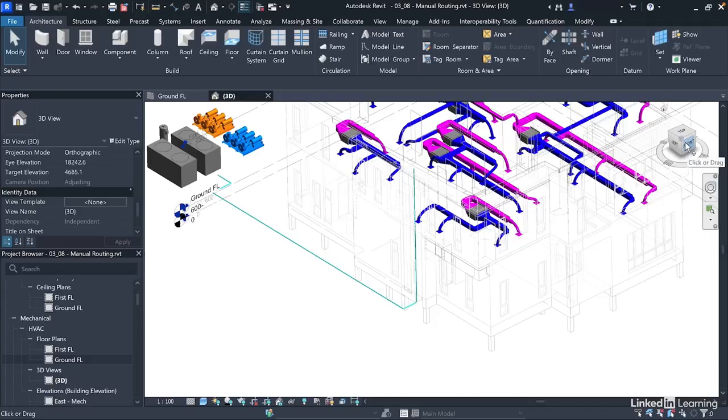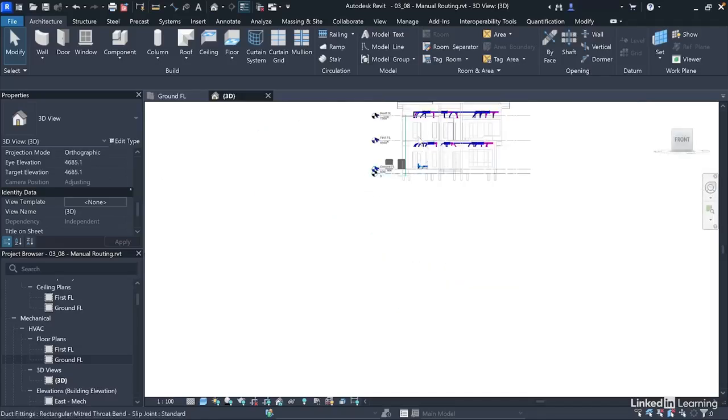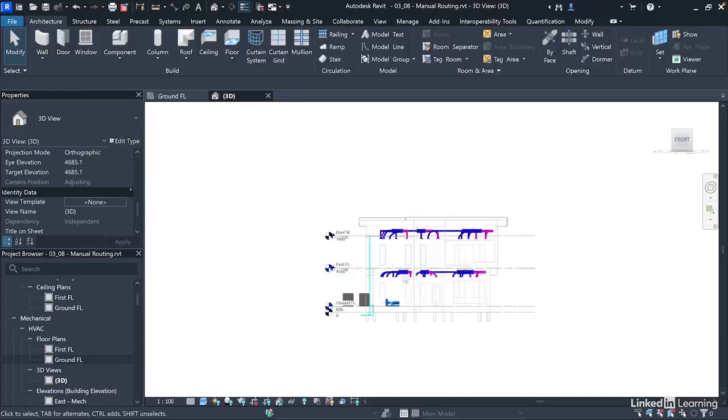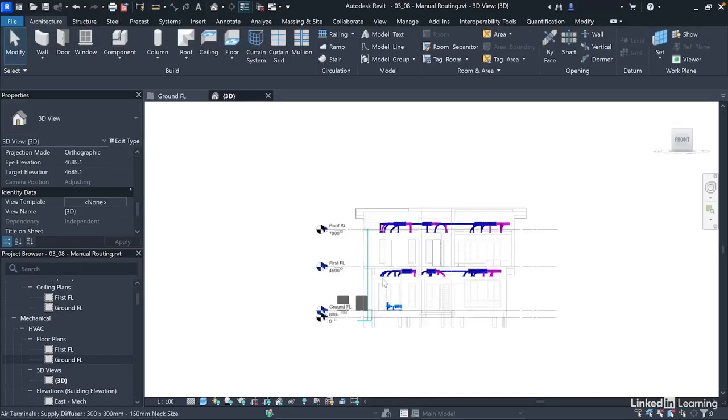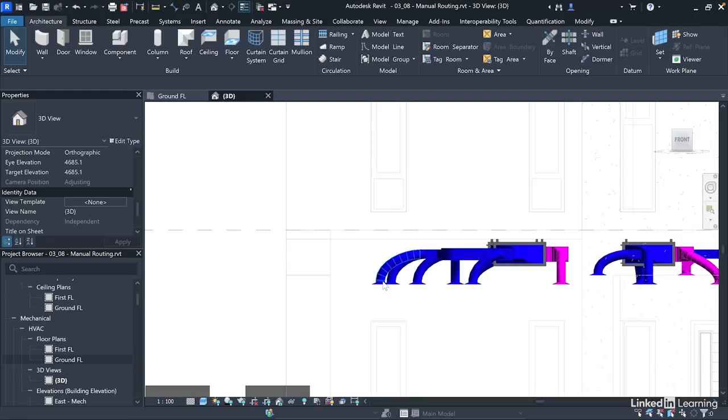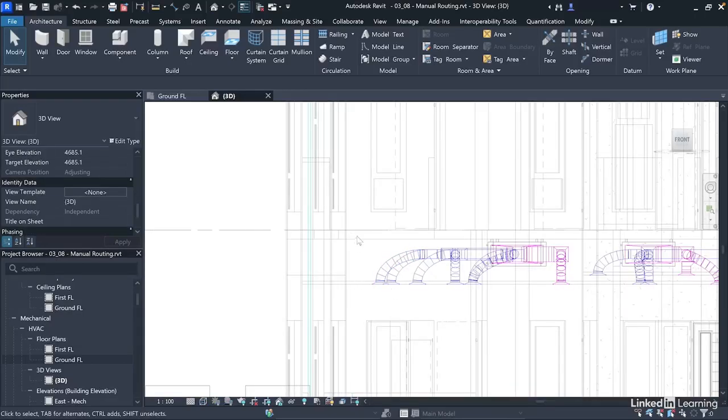For this project, we have about 700 millimeter inside the ceiling above the ground level. So this ceiling here, between the ceiling and the floor here, will have about 700 millimeter, which is quite generous. So since multiple disciplines coordinate in a typical project, the design team should decide early on the middle elevations for the various duct and pipe systems to minimize clashes.